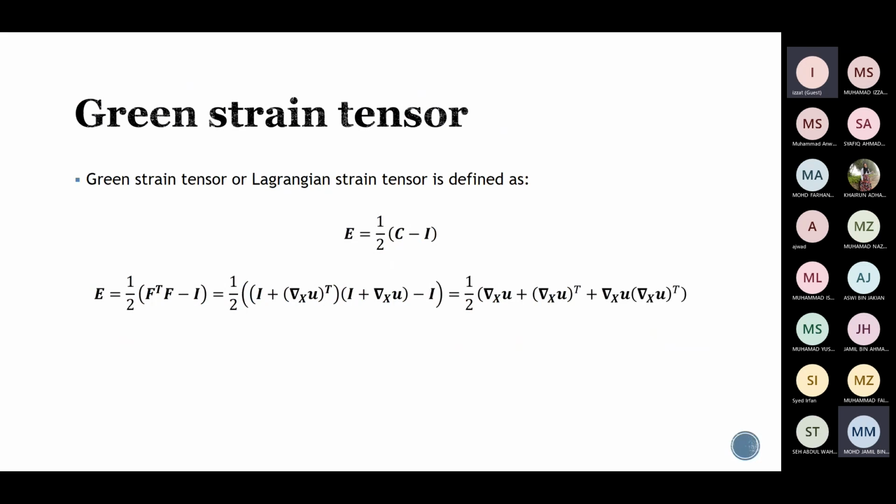So now let's move on to a new definition of the strain tensor. Just now we have the deformation tensor and the stretch tensor. Now we have the strain tensor, only now is it strain. So we have deformation and stretch tensor, but we didn't encounter the strain. So why do we want to find strain? Because later on we will use strain to determine the stress, the stress in the material, not the stress from studying. Studying is certainly stressful.